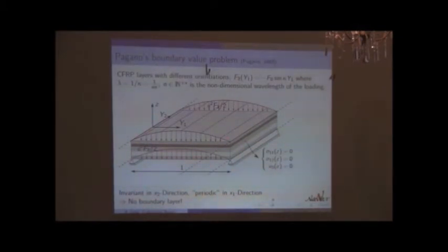The following boundary problem. You have a laminate. It is symmetrically laminated, but he considered a non-symmetric situation as well. You assume that it is infinite in the direction 2. It is loaded on its upper and lower face with a sine shape distribution with respect to the direction 1. And it shows very peculiar boundary conditions, assuming that the out-of-plane displacement vanishes on the support. That's why I've drawn those fancy boundary conditions, but it is a 3D solution, so it's a 3D boundary condition.